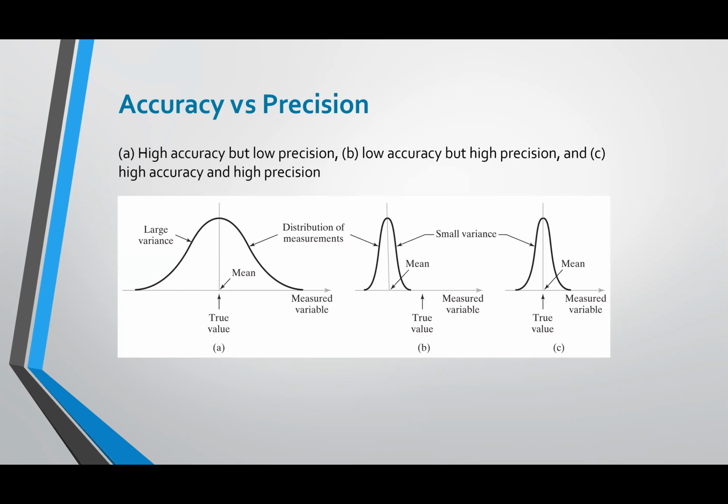So when you look at accuracy versus precision, from a quality standpoint, you're always going to want high precision. You want repeatability. You want to see the same thing over and over, because even if it's inaccurate, if it's very precise, I can just make a small adjustment to move that reading. So maybe I'm getting readings that are supposed to be at 9.5, and I'm getting them over and over, 10, 10, 10, 10. Well, I can adjust that setting down 0.5, and then I would be getting 9.5, 9.5, 9.5.